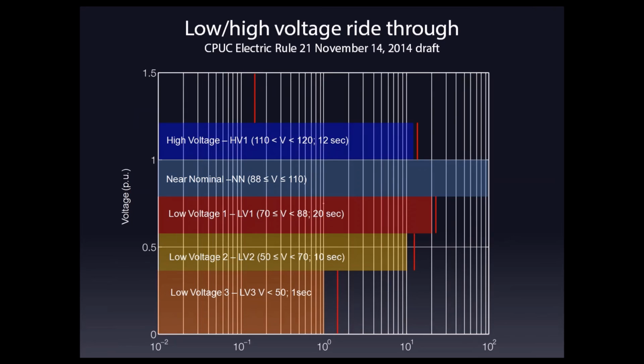So fundamentally, on this graph, if we want to summarize the requirements for voltage ride-through behavior of the inverter, we have 5 critical regions. On the x-axis we have time, and on the y-axis is voltage per unit, because in the US there are different voltage levels, this also applies for single-phase and 3-phase inverters, but it can also be completely scaled.